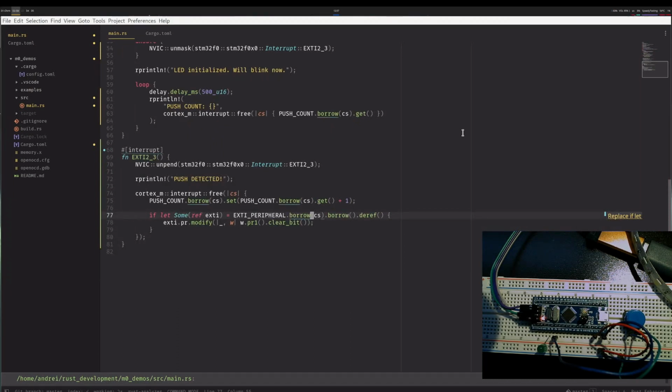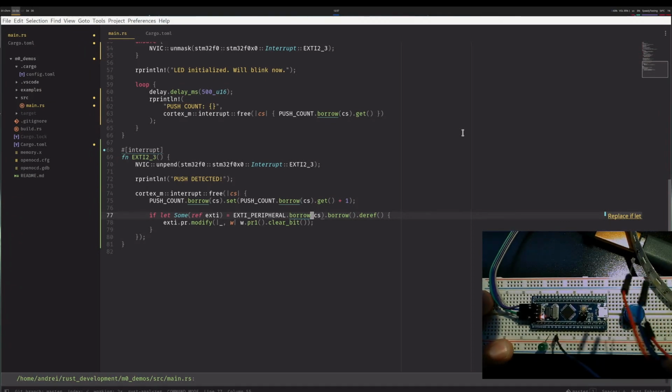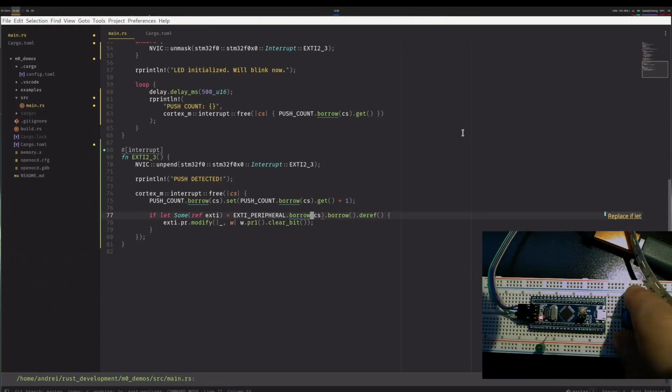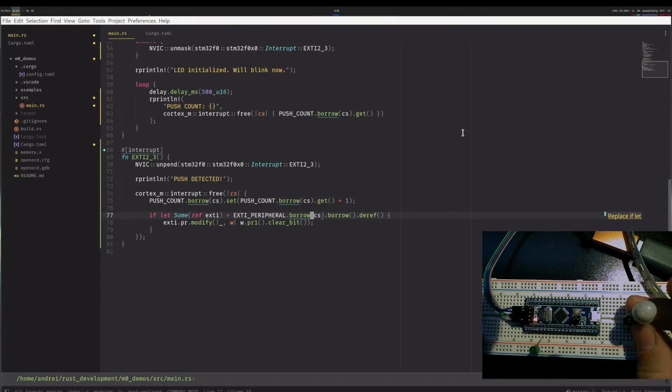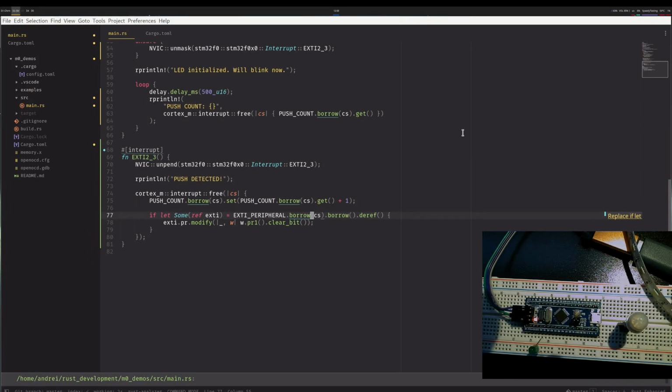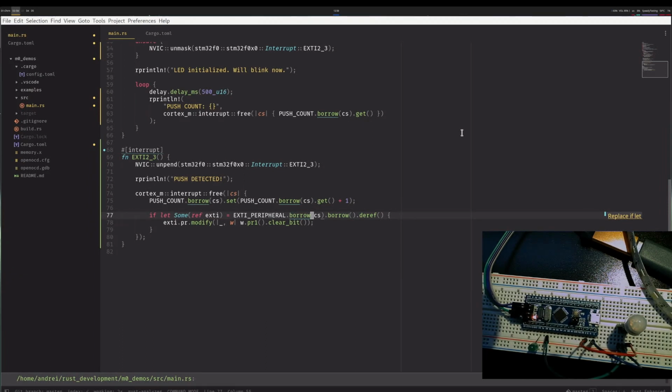Great, so this is the input. This is a simple button input. Now, just as another simple example, you don't necessarily have to have a button as an input, but maybe you have some sort of a sensor. In order to do that, I picked up this simple infrared PIR sensor. This is a motion sensor that uses body heat to detect if somebody is moving or not. It gets powered by VCC and ground. Let me do that. All right, I made all the necessary connections.